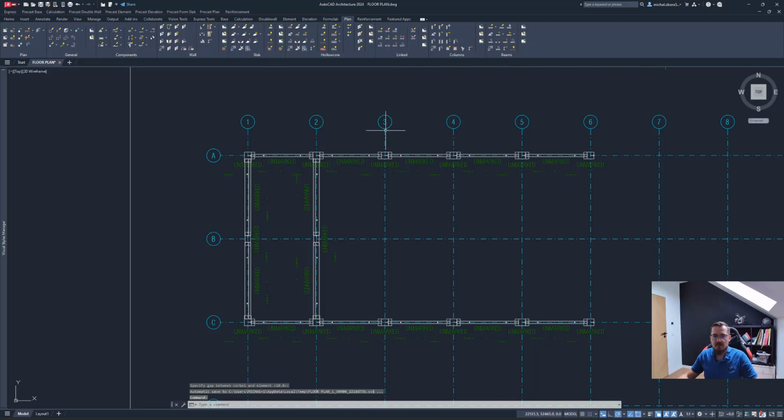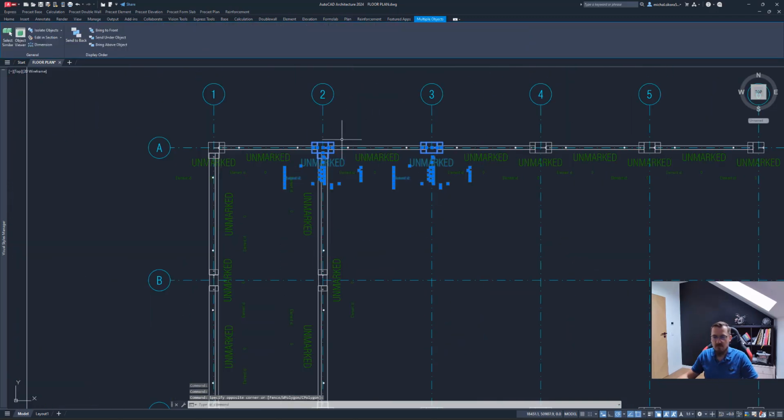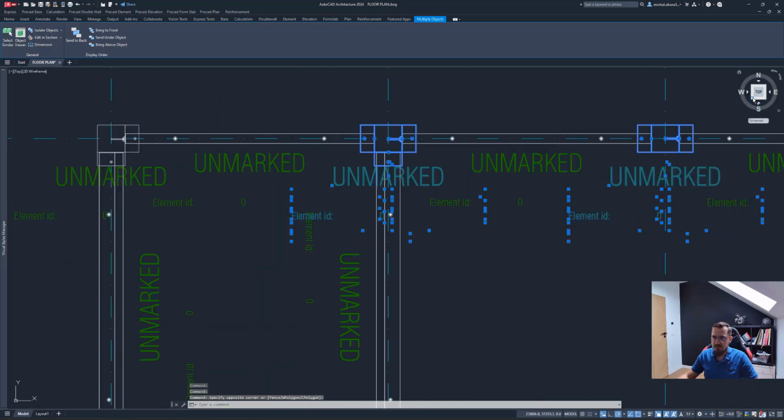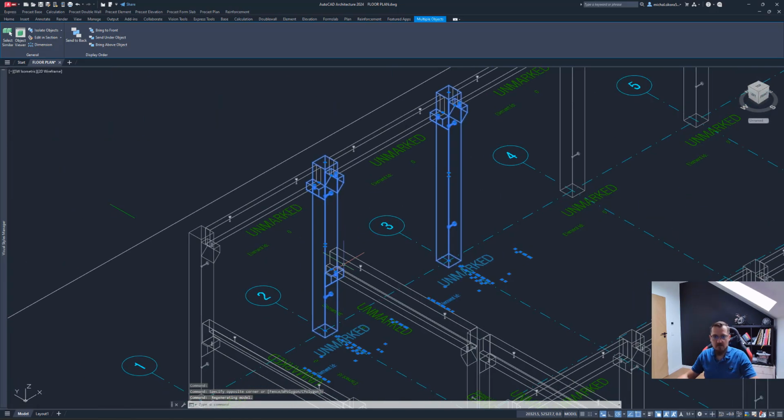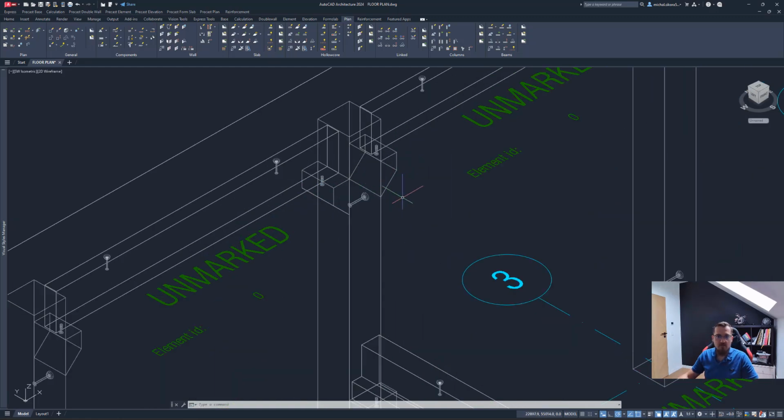As you can see, the corbels have been added to the columns, like so, and it doesn't even matter for the software that those beams are at two different levels and going in different directions. It basically recognizes, okay, this column has beams here and here, we need to support those, and there's a beam as well here on the lower level, let's support the beam as well. So here it is, that's done. The reinforcement of the corbel, we'll be doing that later at the drawing stage actually.